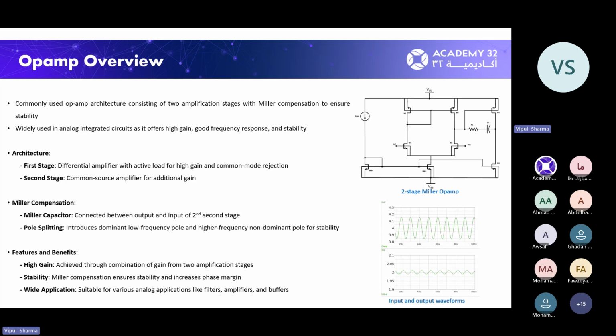One is at the output stage of the differential amplifier, and the second pole is at the output stage of the common source amplifier. These two poles together degrade the phase performance of an op amp. And by the use of this Miller capacitor, pole splitting is encouraged in this configuration, so that these poles move further from each other and a kind of stability balance is realized.